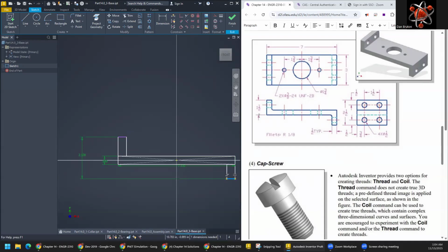It does say that it's 1.5 inches from there to there, so we will assume that that's what we need to do instead of maybe making it symmetric. So there we go. And then we say 1.5. Does that make it fully constrained? Sure does. Let's put the width in there of 3 inches.